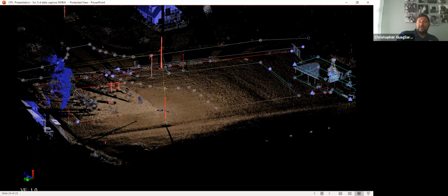So you basically set it up and you have different settings to put on there. You can tell the scanner that I want you to scan every point within 100 feet at 1/100th of an inch, and it'll do it. Anything closer than that 100 feet will be closer than 1/100th of an inch. So if you look at parameters, and the parameter says at 200 feet, you're at 1/1000th of an inch. Everything closer than that is denser. So you have to realize that you're only making that thousandths of an inch out that far. Everything inside is a lot closer than what they got going on there.